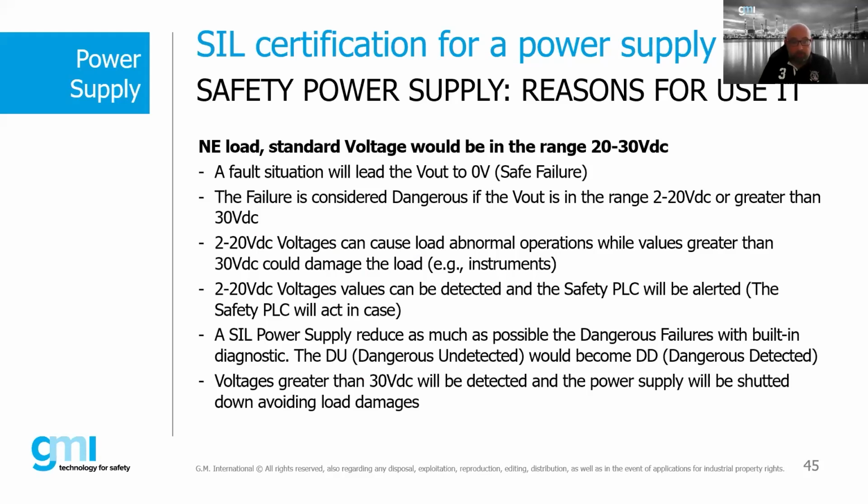A standard power supply can be used in a redundant configuration, but it does not guarantee that our application is safe. When we have to parallel standard power supplies, external components such as an OR-ing diode are required, which means additional wiring, which of course affects the power supply itself and leads to voltage drop in the loop.